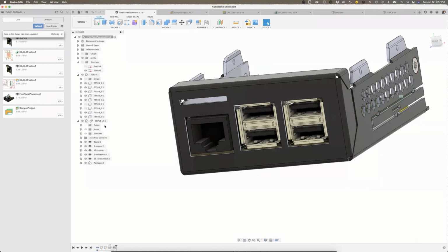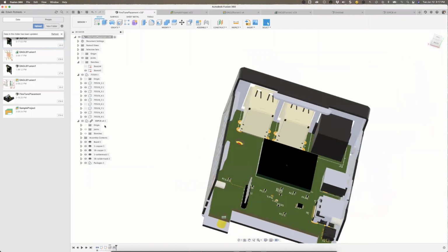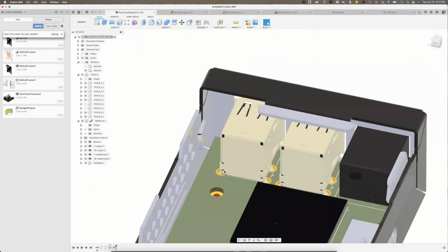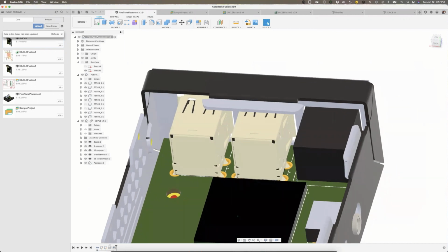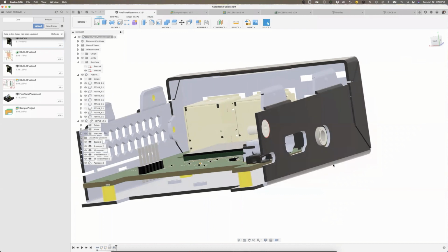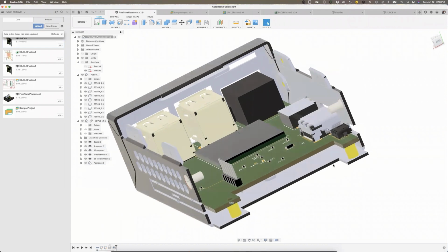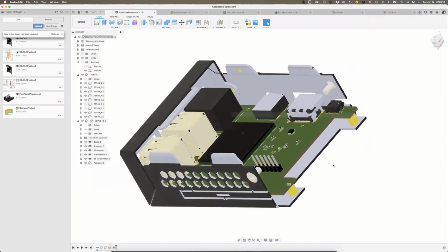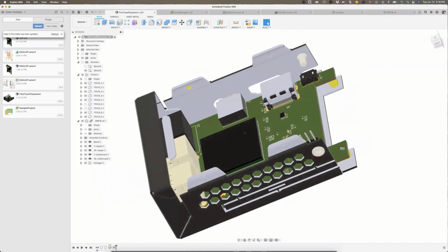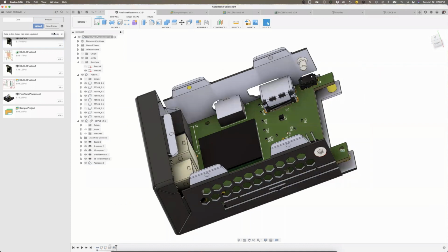Now my 2D PCB and my 3D PCB and the design workspace are completely synchronized, and now we've got a good board. You'll notice that the pads now are nicely lined up, everything lined up as expected. And I could continue doing that with this. This concludes what I wanted to cover today about 3D PCB, the electronic design workspace in Fusion 360, as well as how we could leverage the 3D PCB capabilities in Fusion 360 to really fine tune my component placement.